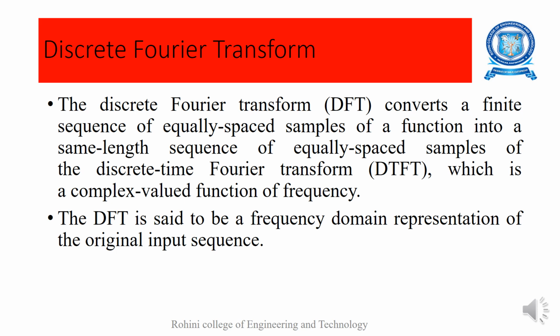Next is the discrete Fourier transform. The discrete Fourier transform converts a finite sequence of equally spaced samples of a function into a same length sequence of equally spaced samples of the discrete time Fourier transform, which is a complex valued function of frequency. The DFT is said to be a frequency domain representation of the original input signal.